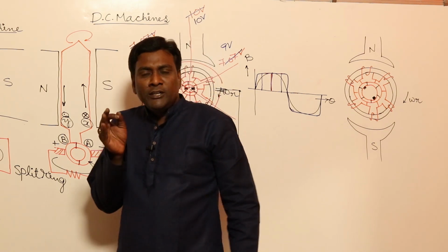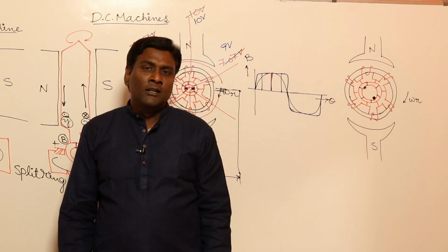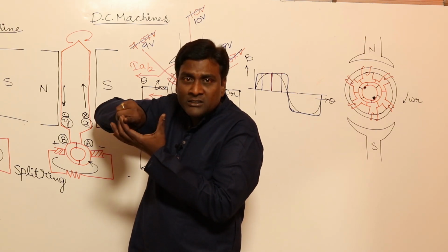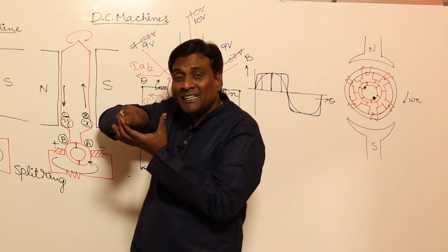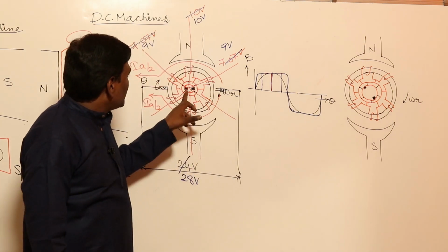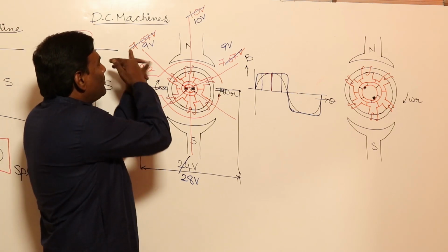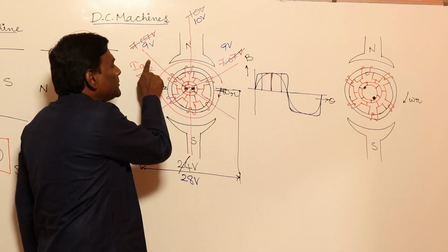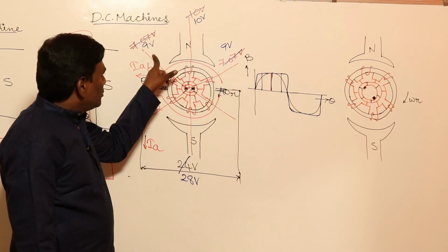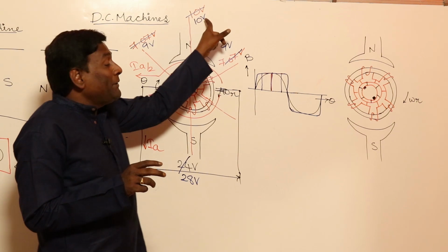Yes. Now insulation, voltage is going to be one of the main design constraints for insulation, right? For a given voltage, these are the conductors, this is the slot, and in between insulation has to be provided. That magnitude of insulation will be decided by voltage or not? Yes. Now that induced voltage will be decided by the peak value of flux density. For example, as of now, induced voltage can be 9 volts or 7.07 volts, depending upon sinusoid or flat top. But once you start the rotation, ultimately this particular conductor has to be placed here and here, because it is rotating. So the magnitude of insulation to be designed will be decided by peak voltage.